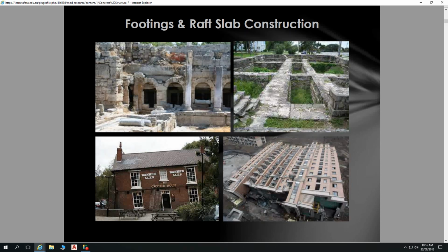But back to our more basic residential stuff. These are our ingredients for making some reinforced concrete. We'll have slab mesh on the top, and that in our beams down the bottom. All right, go make a slab. We want to put some of that underneath our slab. That's to stop moisture coming through, so it's called a vapor-proof membrane.